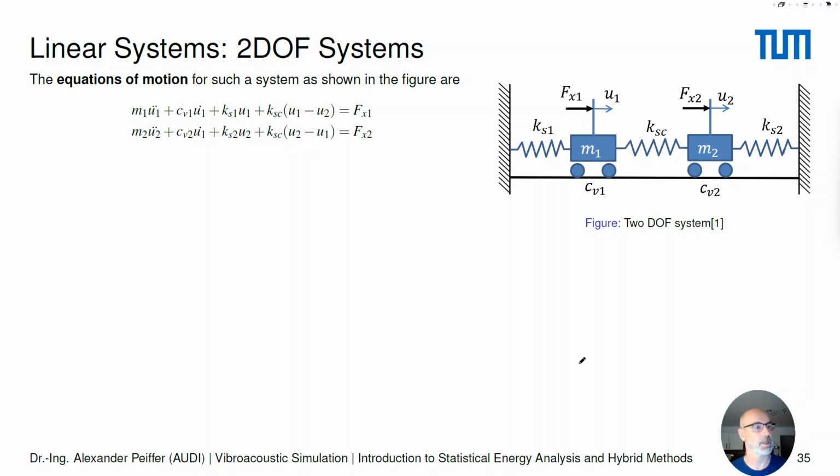So in the first step, we will just use a double degree of freedom system, which is a kind of extension to our harmonic oscillator. Now the arrangement is in a horizontal way. We have two harmonic oscillators, more or less. This is one, and this is the other one. Those harmonic oscillators, which represent the mass and the spring, are coupled by an additional coupling spring in the middle between the masses.